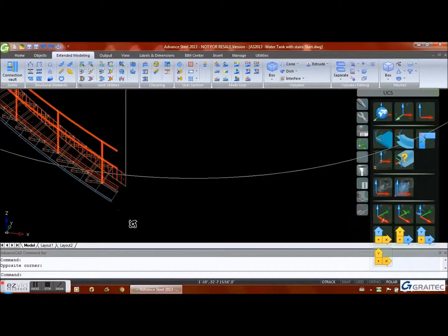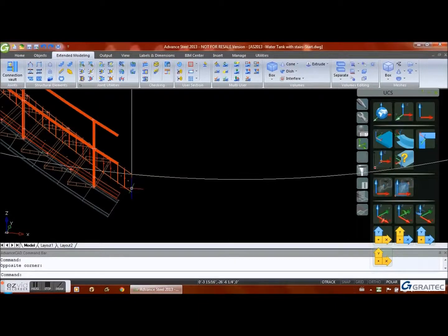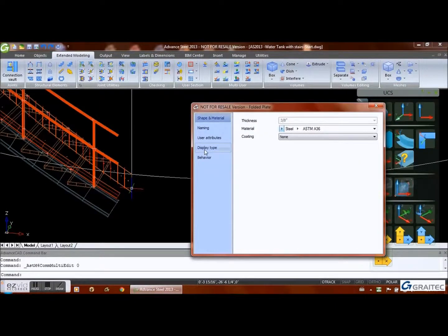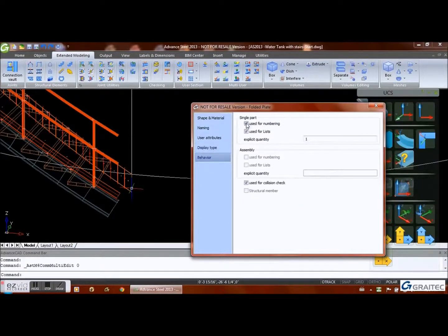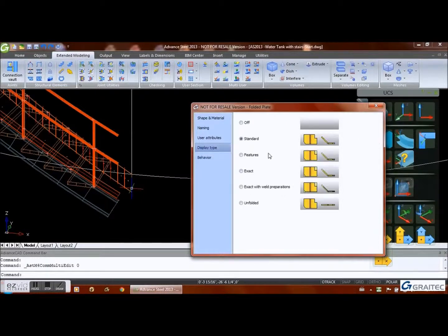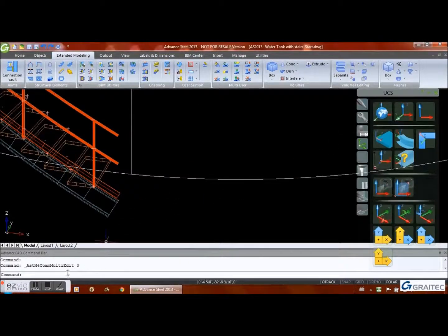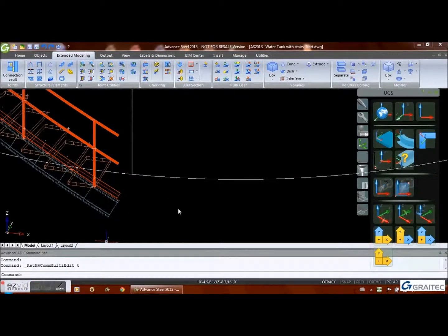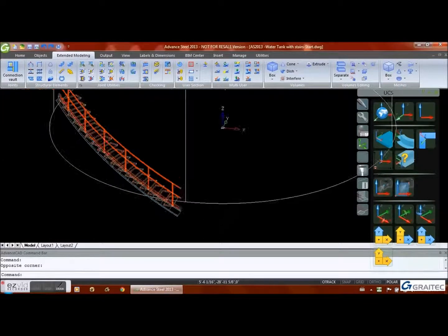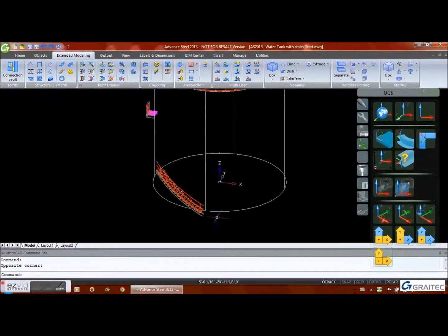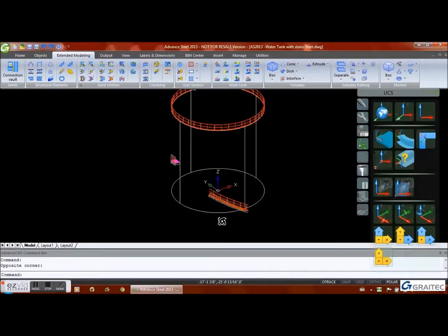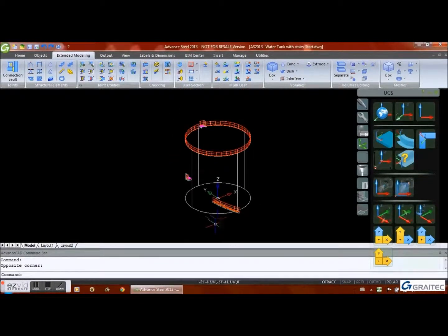As you can see, we need to come in now to the inside stringer, which is plate. We don't need that. So what we're going to do is essentially hide it. We're going to turn off its numbering and its list so that it doesn't create its drawings, and also turn it off. It's also not going to be part of the bill of materials. So essentially it doesn't exist. So now it will not come up in our drawings as single parts.